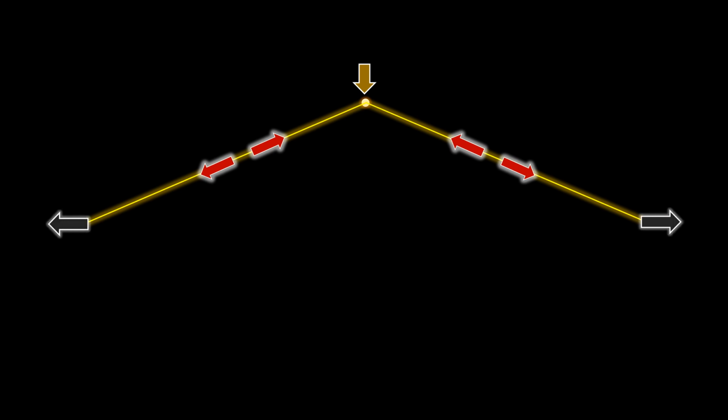Let us talk about lateral forces and the lateral restraint that a pinned connection provides. Suppose we take the same truss and remove the web members and the bottom chord. Please note that the connection at the top is still a pin connection. If a force is applied at the top, the truss members will be under axial compression. Consequently, the supports will experience a force vector which can be resolved into a horizontal thrust outwards and a vertical force downwards. In this type of system, we do not have a choice but to provide pinned connections that can resist both the vertical force and outward thrust.